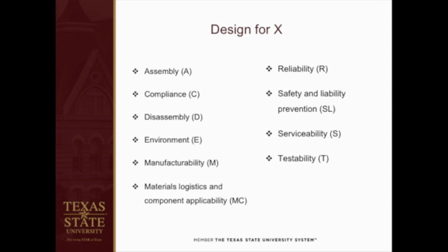Then think about manufacturability. What does that mean? It means that certain things are okay from a design standpoint, from a functional standpoint, but to try to make the stuff would be very difficult. Maybe you need a casting process, but the metal may have a high melting point. That means it's very difficult to melt the metal. It doesn't pour well into a mold.